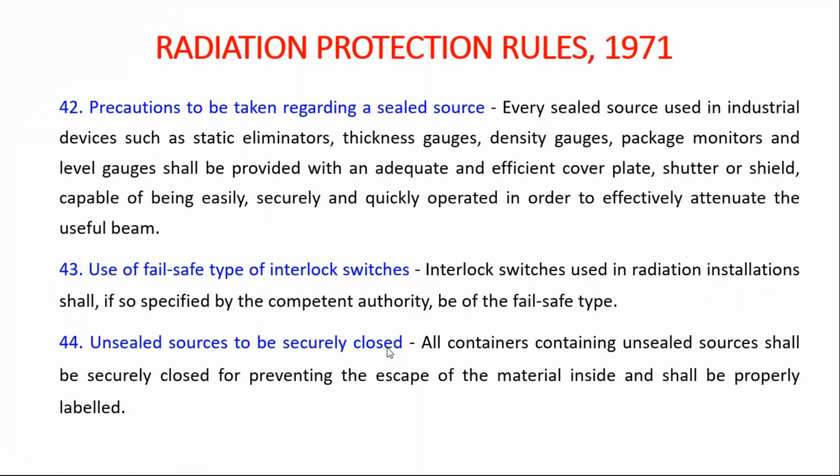Then rule 42 is related to the precautions to be taken regarding a sealed source. Every sealed source used in industrial devices such as static eliminators, thickness gauges, density gauges, package monitors and level gauges shall be provided with an adequate and efficient cover plate, shutter or shield capable of being easily, securely and quickly operated in order to effectively attenuate the useful beams.